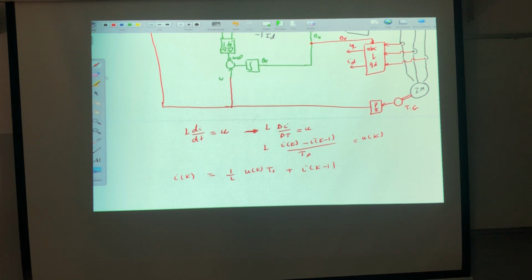Yeah, but it's a valid approach. And by the way, in the literature we have, someone says, I will point the flux toward the stator, not the rotor. Now this one is very simple. If I'm pointing the flux toward the rotor, IDR equals 0. And then omega slip will be very simple. Now, I can do the same, pointing the flux toward the stator.